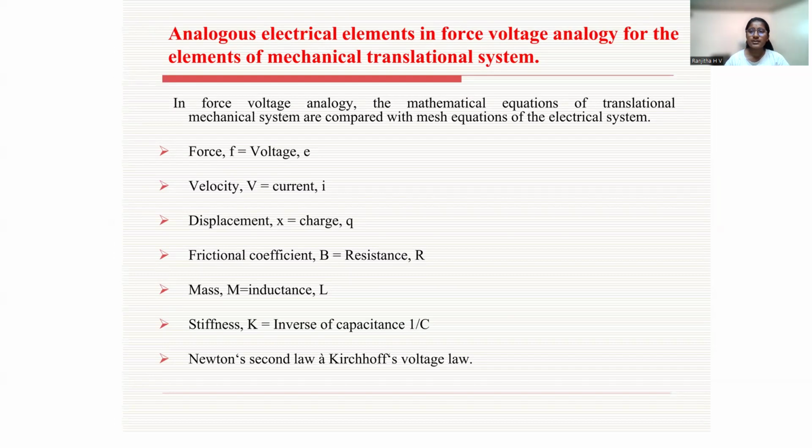The force F is equal to the voltage E, the velocity V is equal to current I, and displacement X is equal to charge Q. The frictional coefficient B is equal to resistance R, and mass M is equal to inductance L. Also the stiffness K is equal to the inverse of capacitance, 1 by C, and Newton's second law corresponds to Kirchhoff's voltage law.